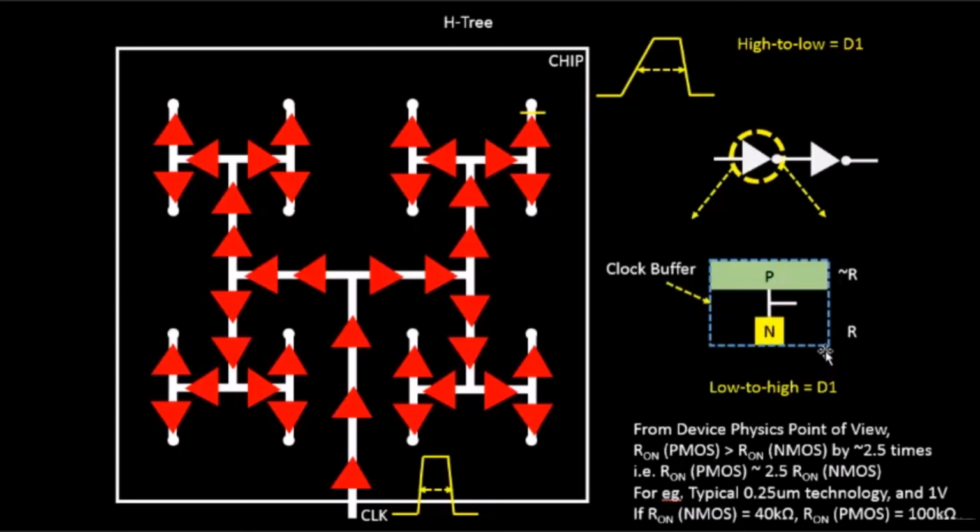So we have to be very careful that while moving into the clock path, or while implementing the clock tree synthesis, the list that we provide to the clock tree synthesis step or the clock tree synthesis algorithm should be clock buffers. We should give the clock buffers list for the clock tree building, and this is a very obvious and very important reason.